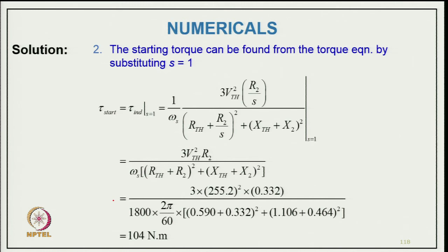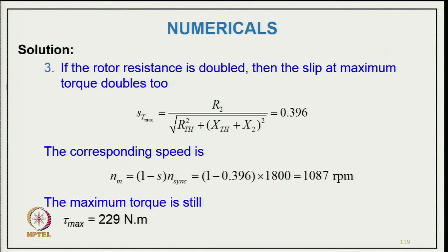And coming to starting torque, it can be found from the equation by putting S equal to 1. Putting the value S equal to 1 here, we get 104 Newton meter.